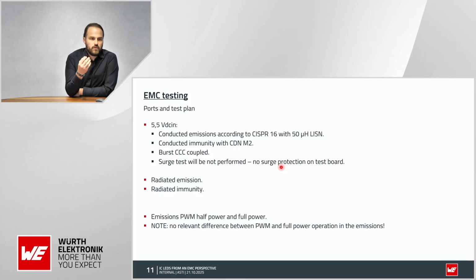A surge test we will not perform, because I guess for such a board or lighting equipment you will have a short connection between your AC/DC power supply and your board later on. Then we will do the radiated emission and immunity testing, of course. And then the question is, you have different possibilities for how you can power up these LEDs.